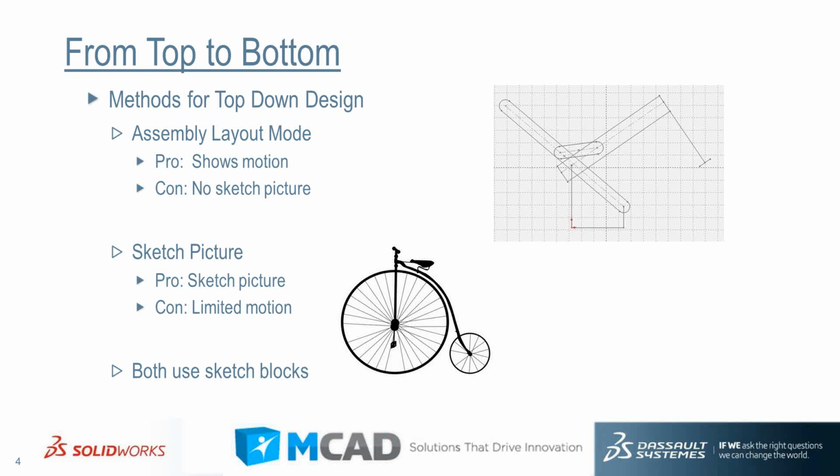Now the next method I'm going to show you is a sketch picture, and basically what you get is an overall image of the assembly that you're going to be building, and you use that to start creating all your in-context parts, and you're following the picture within that. Now the sketch picture is really nice because it gives you the look and you can refer back to it every time, but unfortunately you can't really do any motion inside the sketch picture until you're completed with all the component sides. So you could create the 3D components in the assembly and then you introduce the motion inside there.